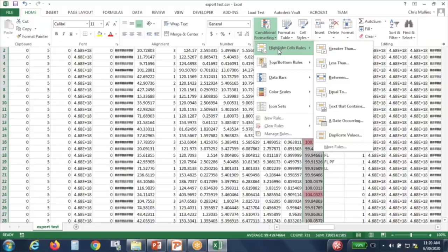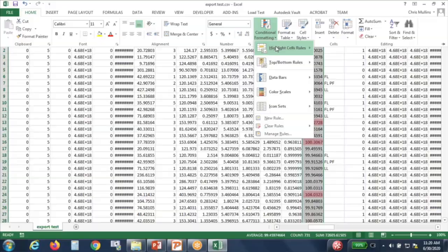Does anything explain that? Imbalanced load possibly, 2 amps on A, 2 amps on B, hardly anything on C. Could that affect the meter registration? Possibly. It would be unusual, but it's possible. This one's slightly out, it was 100.3%, but notice that I've got no current on C phase either.